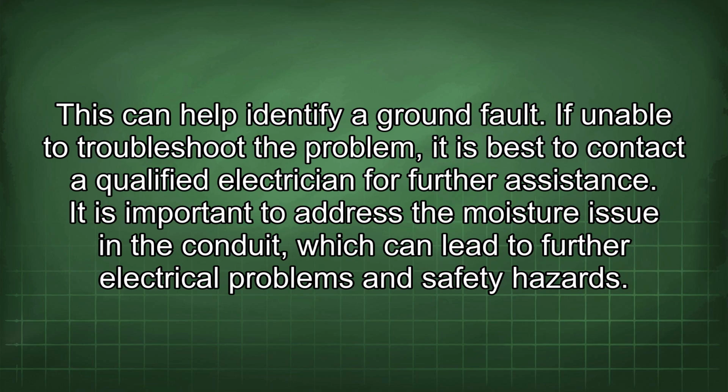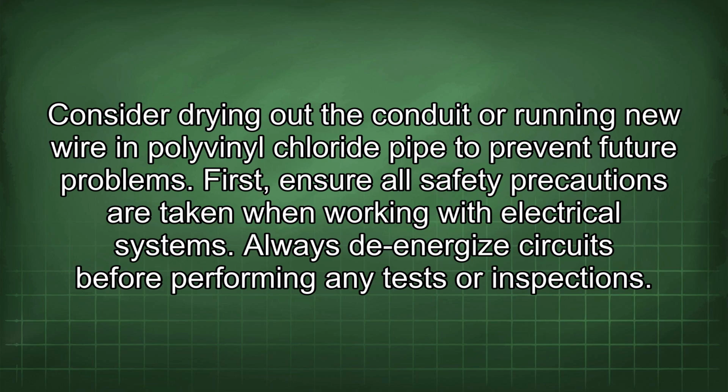It is important to address the moisture issue in the conduit, which can lead to further electrical problems and safety hazards. Consider drying out the conduit or running new wire in polyvinyl chloride pipe to prevent future problems. First, ensure all safety precautions are taken when working with electrical systems. Always de-energize circuits before performing any tests or inspections.